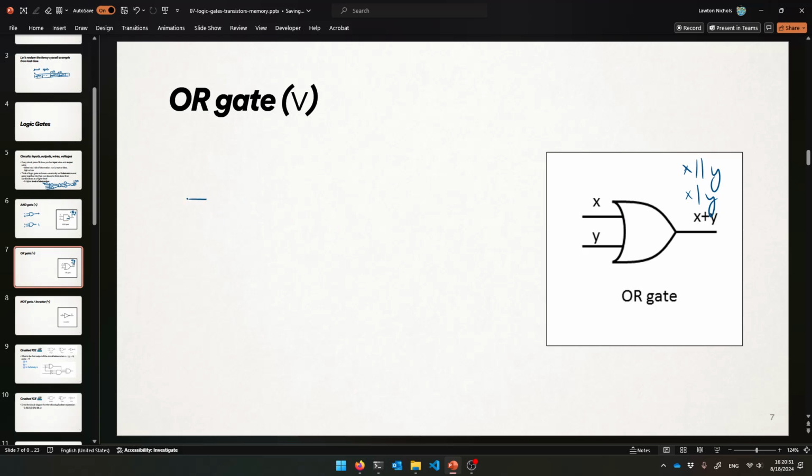All right, so if you're feeding into an OR gate, what does it look like? Well, if you give a 1 and 0 now, for sure the output's 1. That's great. It's a 1 as long as there's a true coming out of somewhere. So true ORed with false is totally true. And the only way to make an OR gate give back a 0 or false is if both inputs were a 0, right? That's the only way for an OR to give back 0. Okay, so that's how I'll draw those.